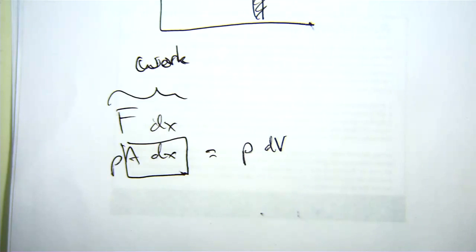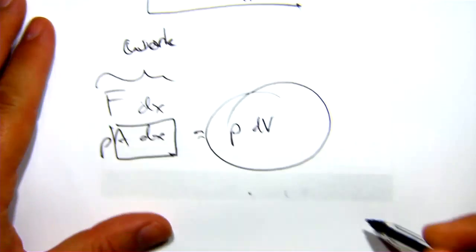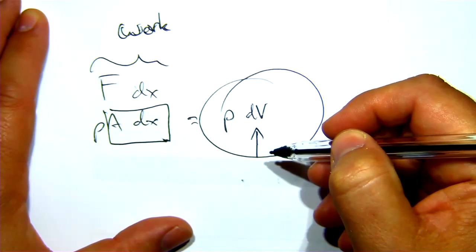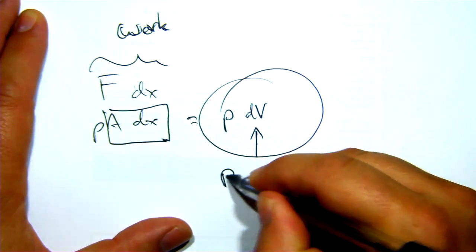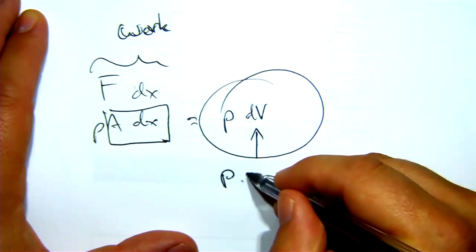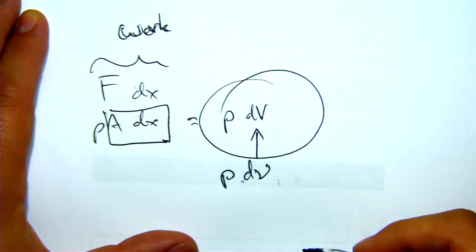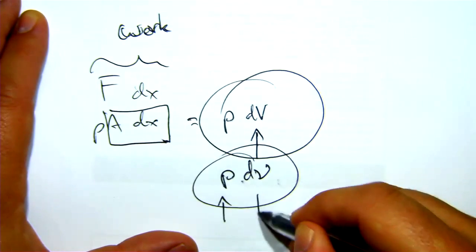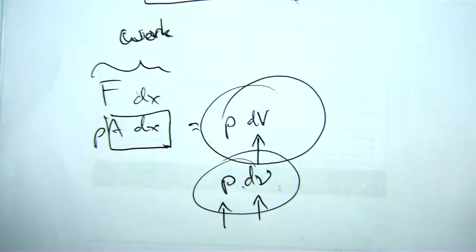And also, more importantly for this guy, I operate on a per mass basis, which means that I can write the per mass work done as P d change in specific volume. This is now in terms of two intensive independent properties, which means I have an expression for work in thermodynamically useful units.